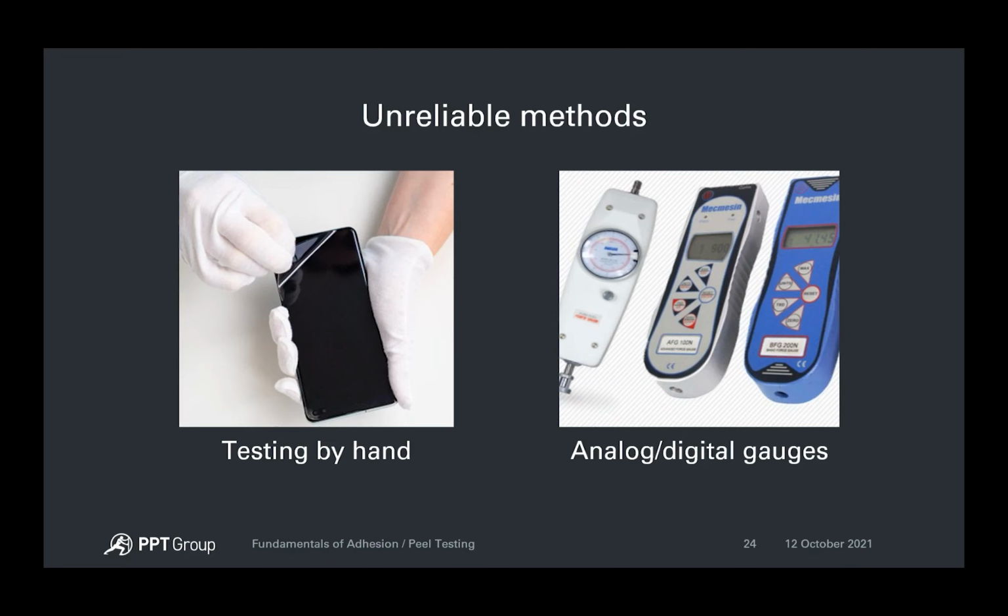And mechanical or analog gauges make use of springs to convert the magnitude of force being measured into a calibrated force value that is displayed by a needle position against the graduated dial indicator. This type of force gauge is durable, simple to use, easily transported, and being mechanical in nature, it doesn't require electrical power to operate. But they have a few limitations. First, while they display results on the dial indicator as force conditions change, they're not capable of sampling and holding different values over time. Most devices can hold a peak value only.